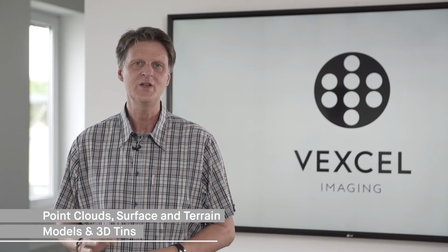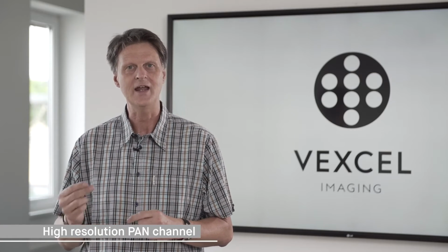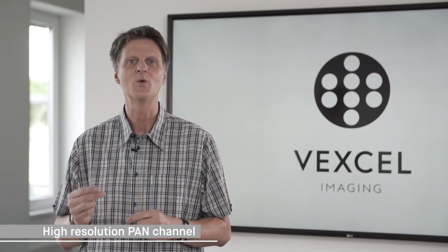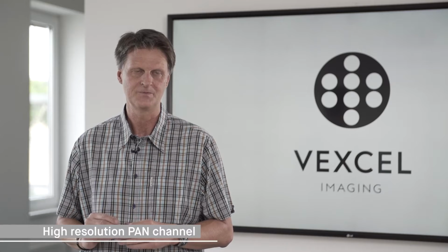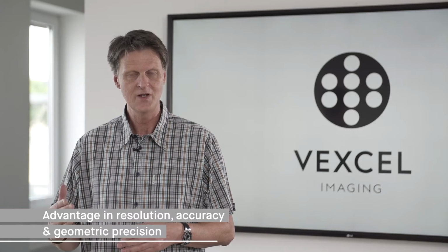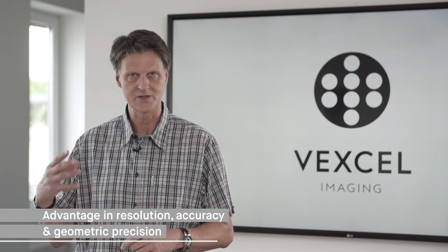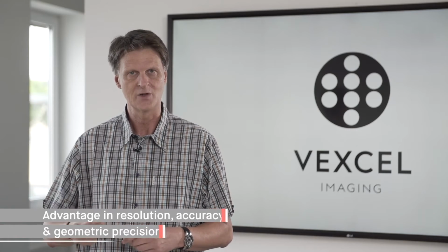The very unique feature of the UltraCam Osprey is the pan channel. The camera is the only oblique camera system on the market which is using a high resolution pan channel, and this pan channel acts as a photogrammetric backbone of the camera system. That has a significant advantage in resolution compared to the use of RGB Bayer pattern sensor, but not only in resolution, also in accuracy and geometric precision.